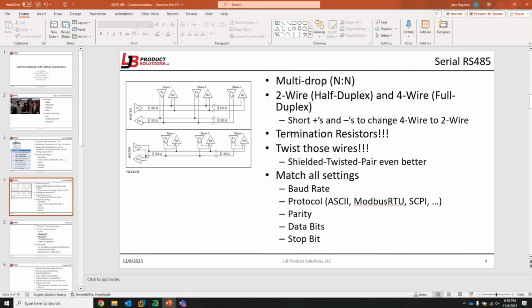So a particular PLC that I have has a termination resistor, and it just tells you in the documentation if you wish to enable it, jumper the TX plus or the data plus back to the termination. That'll handle that end. This particular USB device that I have has a termination resistor built into its breakout board, so that made it real easy.